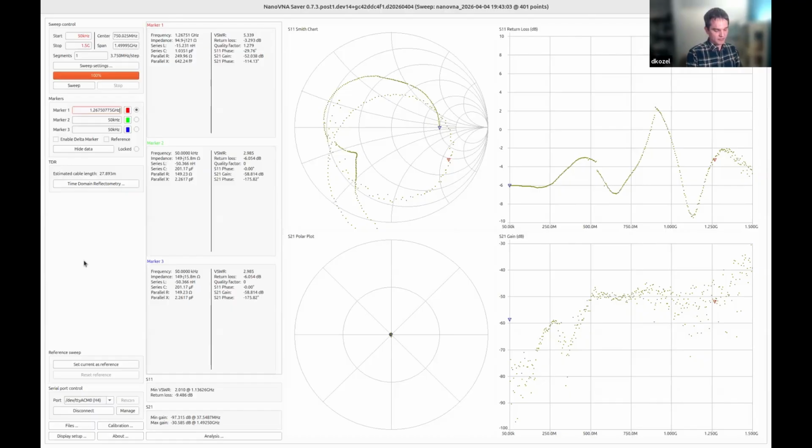So now I'll connect it straight through, and on the gain through, again, we're seeing essentially no power come through. It's still sitting at -80 to -50. What we can see, though, and I should emphasize this, is that because it's an open circuit, it stays at basically exactly -6, within essentially measurement error, up to 250 megahertz, but then we start oscillating.